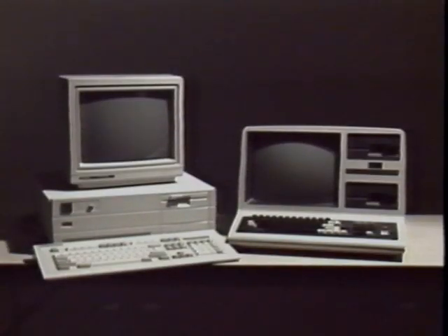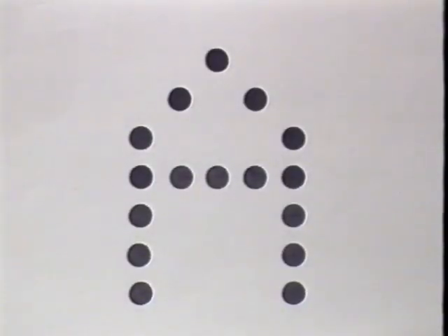In this package, we will examine and discuss standalone monitors, but most of the information is valid for monitors that are part of an integrated computer unit. Let's start our discussion of monitors with a look at some of the major parts found in them. A CRT, or cathode ray tube, is the basis of the video monitor. Inside of it, an electron gun generates a beam of electrons that strike the luminescent faceplate, forming tiny dots of light. These dots make up the alphanumeric and graphics data that we see on the screen.